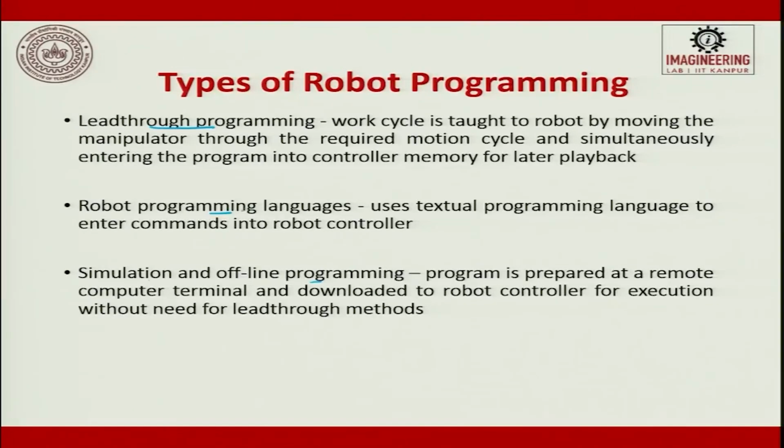Next is robot programming language. We use a textual programming language and enter the commands to tell the movement of the robot within the work volume. Next, simulation and offline programming. The programming is prepared at a remote computer terminal and downloaded to the robot controller for execution without need for the lead through method. So, this is an interesting thing.